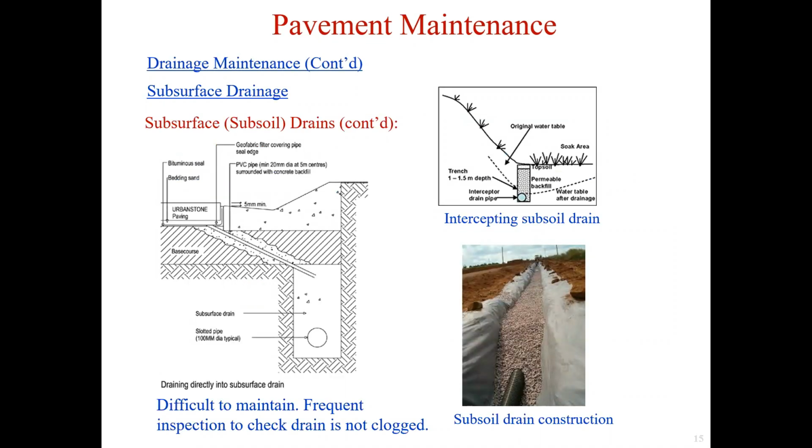It is difficult to maintain the subsoil drain. Frequent inspection to check the drain is not clogged is needed. If necessary, drains should be dug out and relaid using a properly designed filter material.